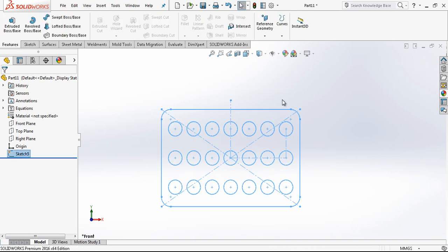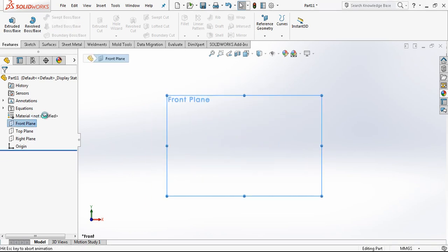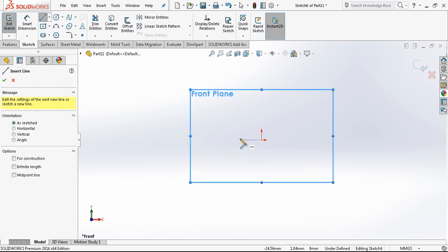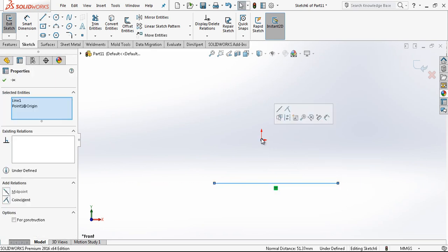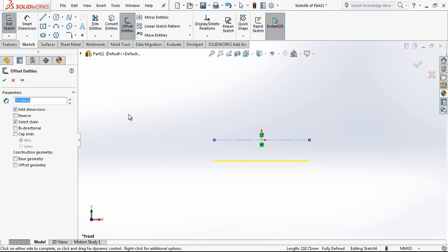And this is also done, and we have a couple more objects I should define, which is offset. Again, my way is to have a line here, bring it in relation to the middle point, turn it into a construction line, and choose offset.